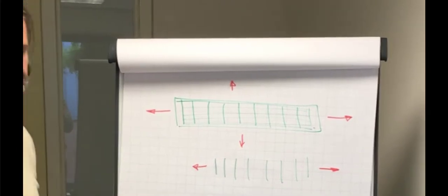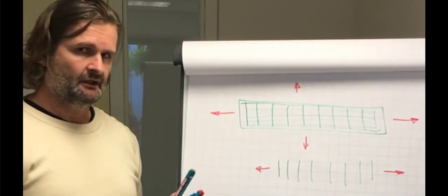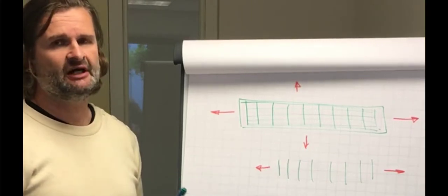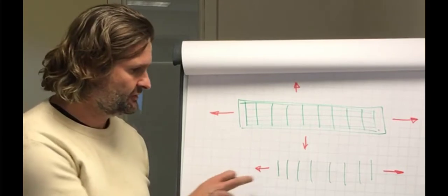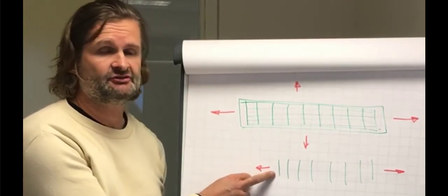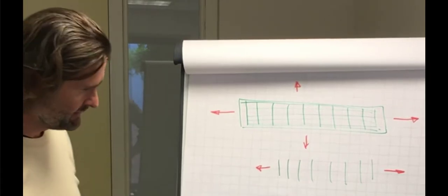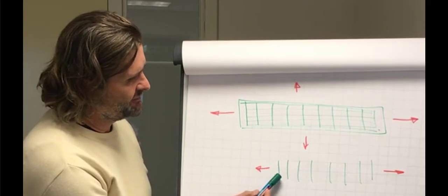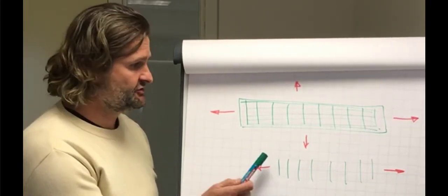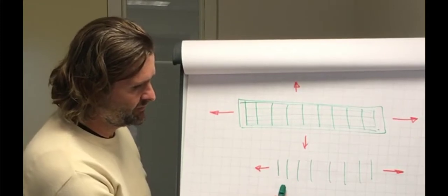That deformation is not high because the fibers take a load, but it is still there. And contrary to what you might think, glass fiber is very flexible. A glass fiber composite is even 10 times more flexible than steel. That means for any given load that the deformation is also 10 times more than you would expect for a steel pipe. And that gives the following effect. That means that the fibers that are in the wrong direction, so in the layer that has the vertical fibers, they will be moving outward.